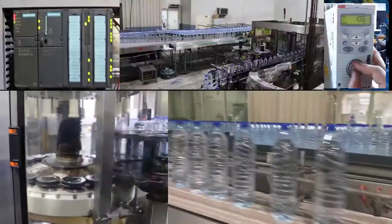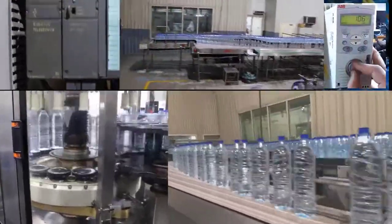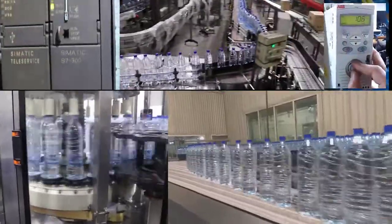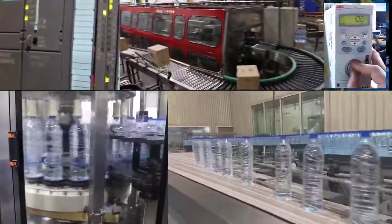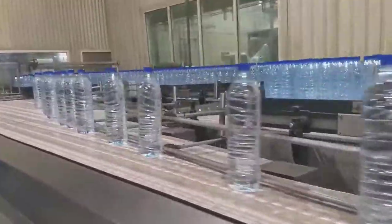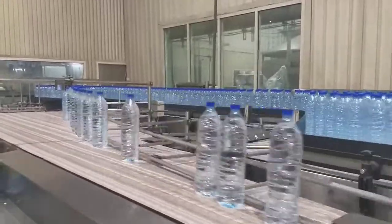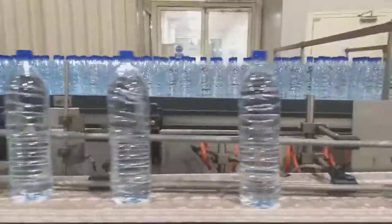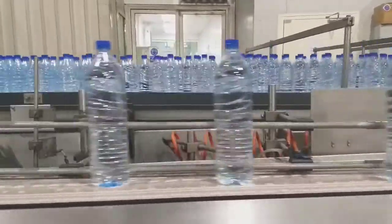Now let's talk about some industrial applications where we are actually using VFDs. Let's go to the packing industry and try to find whether we are using any VFDs there. Yes, in conveyor systems we are using VFDs. And what is the benefit of using VFDs? By using VFDs, conveyor speed can be changed to the most suitable value according to the workpiece. VFD is also allowing us the soft start and stop, and that prevents the products from falling down.